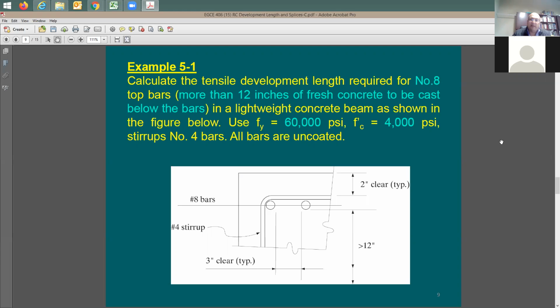So you don't really need to weld it. You don't do anything to it. What's going to happen is the force is going to come out of the first rebar into the surrounding concrete, and then get transferred to the other rebar, also through the surrounding concrete.